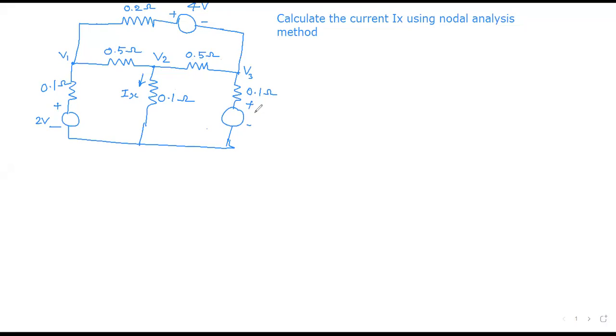should be current sources. Before going to solve the problem, we should ensure that the circuit has current sources. Okay, look at the circuit diagram. We have three sources, right? There is one 4 volt, 3 volt, and 2 volt. These are voltage sources. The 4 volt has a plus minus symbol. So all three sources are voltage sources.